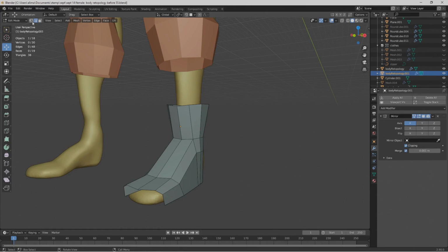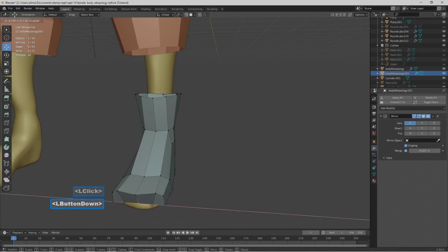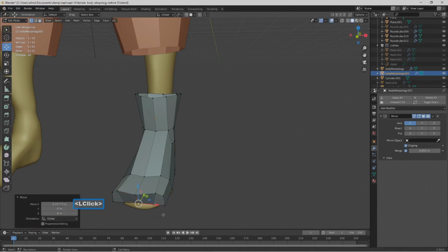Okay, I'll go to the upper left, go to vertex select, hold the mouse button, rotate, select here, hold Shift, press D, right click, push this vertex over, hold Shift, press D, right click, push this vertex over short of the center line. I'll select here, hold Shift, select here, here, as well as here. With those selected, I'll press F. I'll select here, hold Shift, select here, here, as well as here. Press F to fill. I'll select this vertex, then push this towards the center line. Then I'll left click to deselect.